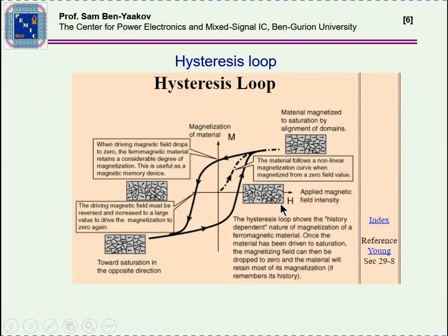Now the reason for the hysteresis loop is the fact that the ferromagnetic material is built of magnetic domains, which, as we increase the excitation magnetic field, are rearranged inside the material, and this rearrangement entails, so to speak, some friction, and this friction brings about this magnetic loss.